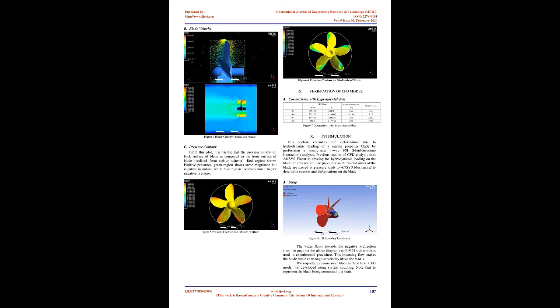Where v is the relative velocity, the velocity viewed from the moving frame, and omega is the angular velocity. Note the additional terms for the Coriolis force and the centripetal acceleration in the Navier-Stokes equations. In Fluent, we'll turn on the additional terms for a moving frame of reference. For more information about flows in a moving frame of reference, visit ANSYS Help Viewer, Fluent Theory Guide 2, Flow in a moving frame of reference, and ANSYS Help Viewer, Fluent User's Guide 9, Modeling flows with moving reference frames.